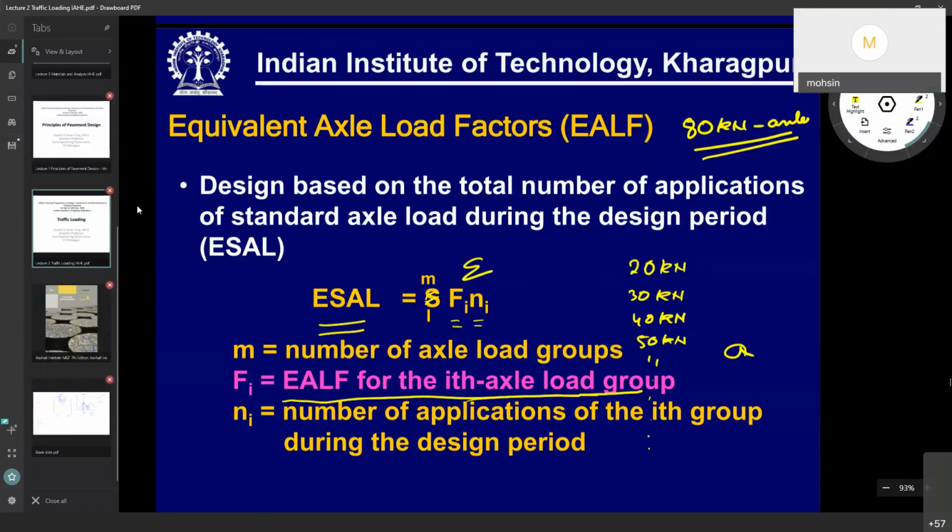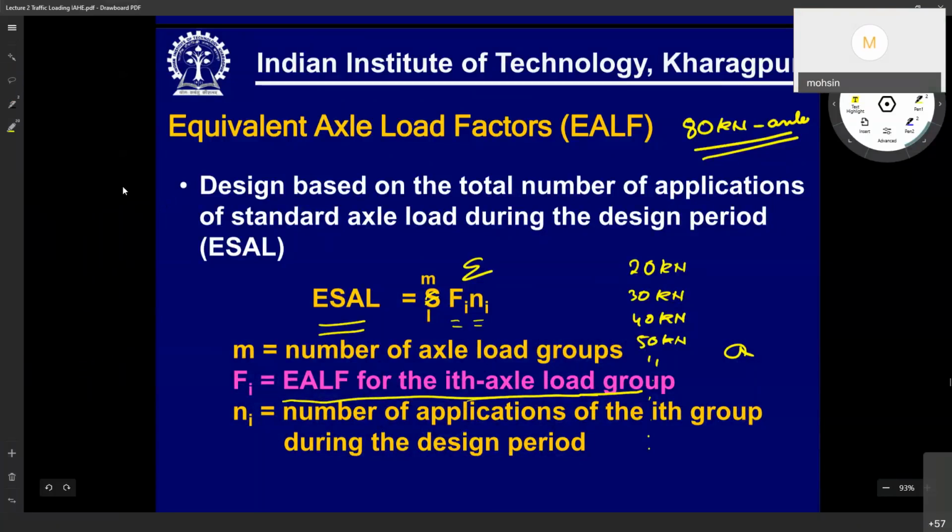Hello. Yes. Sir, do we see these criteria for the rural roads also? Because in the rural roads, we see only the CBR and the traffic category, T1 to T9. Then from the catalogs, we develop the pavement thickness, base and sub-base. So what is the use of these rutting depth and other parameters which you are showing, the applicability of these for the rural roads, like the PMGSY?